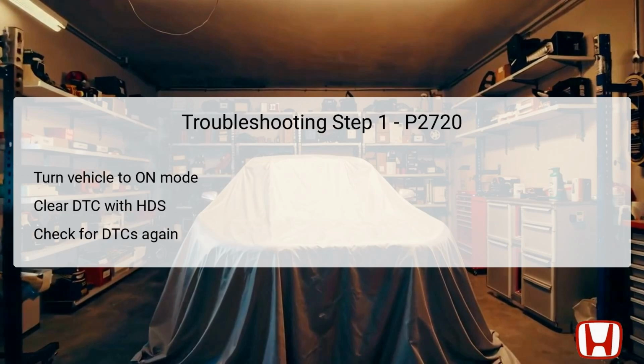The first step in troubleshooting DTC P2720 involves verifying the problem through initial checks. Begin by turning the vehicle to the on mode without starting the engine. This action powers up the vehicle's computer systems. Next, use the Honda Diagnostic System, HDS, to clear any existing DTCs. Once cleared, start the engine for at least 1 second. It is essential to check for any pending or confirmed DTCs again with the HDS. This step serves as a means to confirm if P2720 is present.